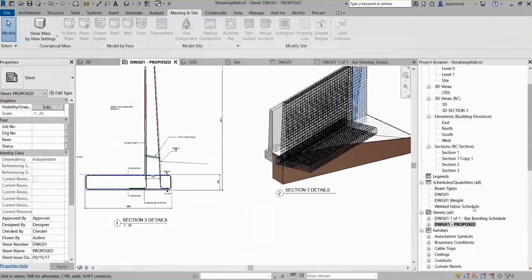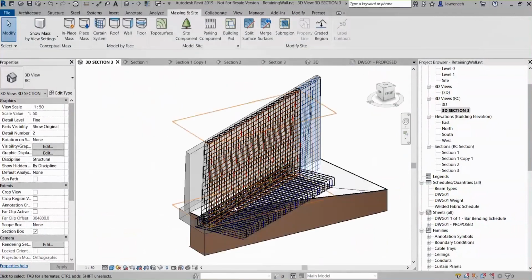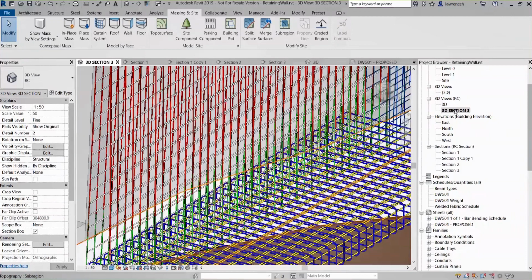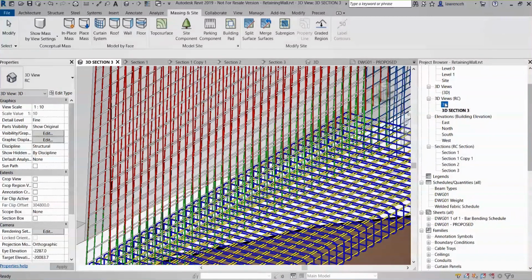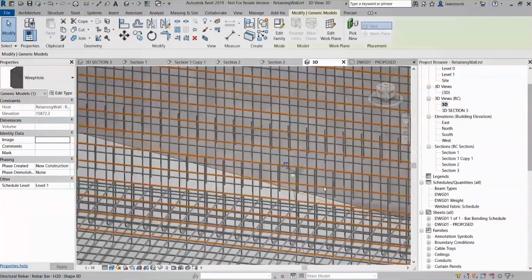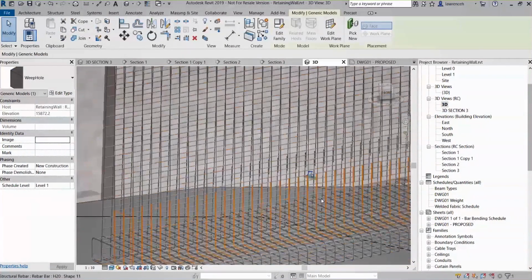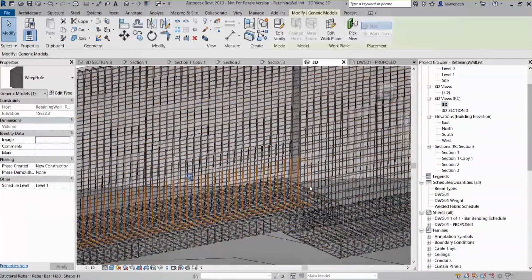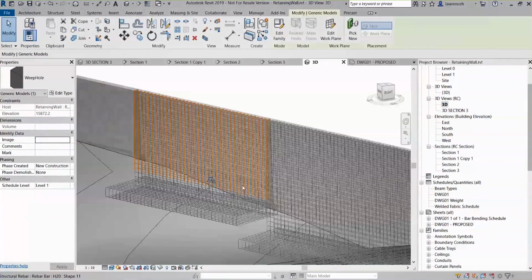So everything, the workflow has worked really nicely, going from Civil 3D, BIM 360 into our Revit model. The other good thing to remember is if I tweak and change that Civil 3D surface, it will automatically update our Revit model because it's hosted in BIM 360.